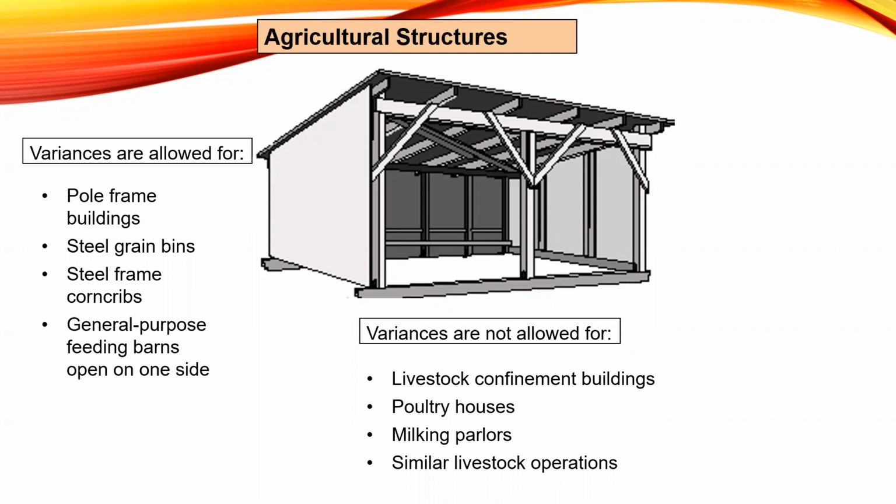So the community ultimately has authority to grant variances, but there's quite a bit in the new FEMA full publication P-2140 that I'll show you. They're really trying to move away from those types of agricultural structures because they're not low damage potential. There could be safety issues for the animals in that case. Things could leak out into the floodwaters as far as ag chemicals that could be dangerous or hazardous and that kind of thing. So if you're not sure, I would definitely take a look at that publication.